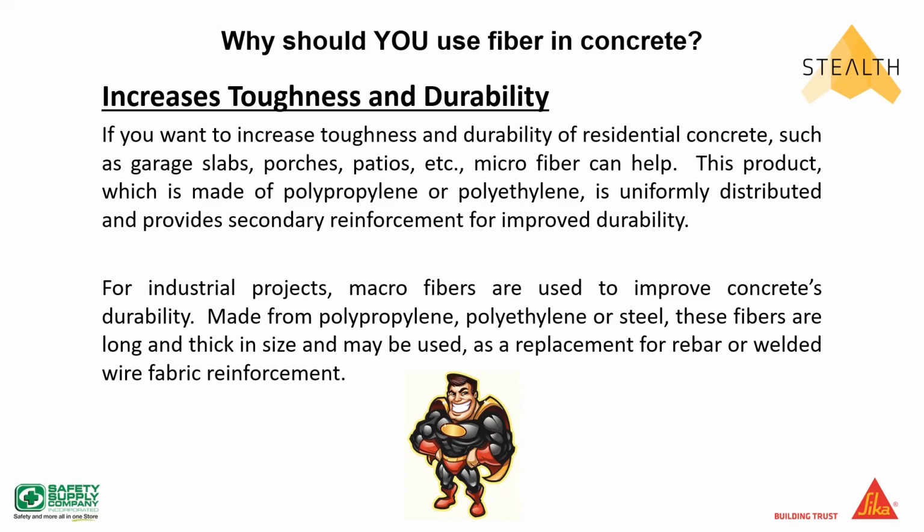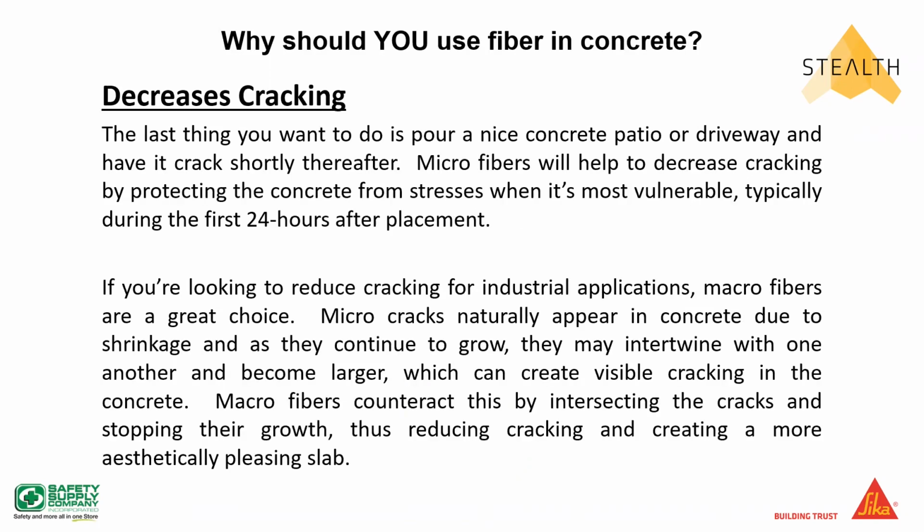So we can mix and match, and we'll even talk about this thing called blended fibers, where we have macro and micro combined in the same product. But first reason why you need to consider using fiber in your concrete: increases toughness and durability. Again, here's a big one: decreases cracking. Whether it's the early age plastic shrinkage cracks or temperature cracking, it reduces cracking. If you're looking to reduce cracking for industrial applications, like I said, macro fibers, great choice for that. So certainly, it addresses your cracks.